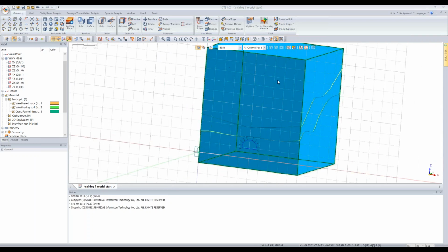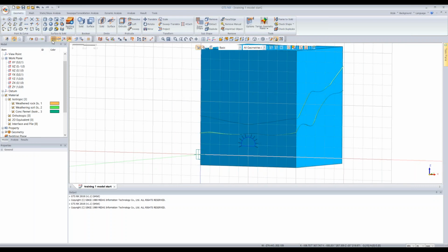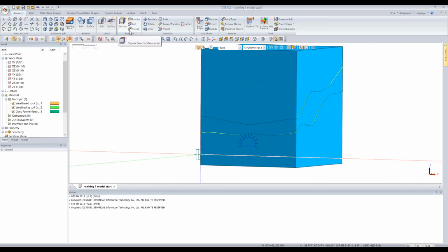From there, what we would do then is just take this 2D drawing and make a 3D shape out of it by extruding. So I am actually done with the grid, so I can deactivate it again up here by the work stream, right where the work stream meets the icon commands. There's a little icon for the grid. If I click on it, it'll hide it. And now I want to go here on my top menu, look for the command extrude.